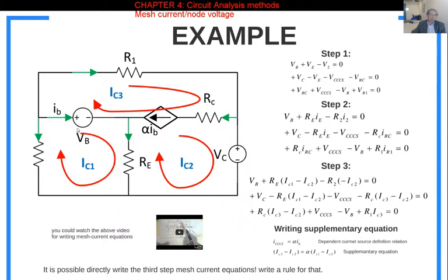This is an independent voltage source. Voltage, it is a known. So you can write this voltage there as a known. In linear equations, these are the known values. Another known value is VC, this independent voltage source voltage, which should be given to you as a function of time. If it is a DC, it's going to be a constant. So that VC, wherever you see it, you're going to replace this voltage with that value, which is given to you. So VB and VC are known.